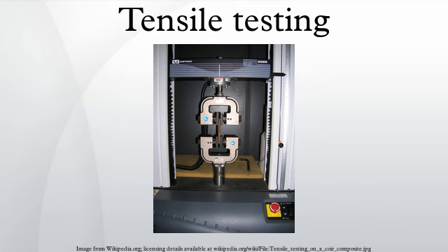The shoulders of the test specimen can be manufactured in various ways to mate to various grips in the testing machine. Each system has advantages and disadvantages. For example, shoulders designed for serrated grips are easy and cheap to manufacture, but the alignment of the specimen is dependent on the skill of the technician. On the other hand, a pinned grip assures good alignment. Threaded shoulders and grips also assure good alignment, but the technician must know to thread each shoulder into the grip at least 1 diameter's length, otherwise the threads can strip before the specimen fractures.